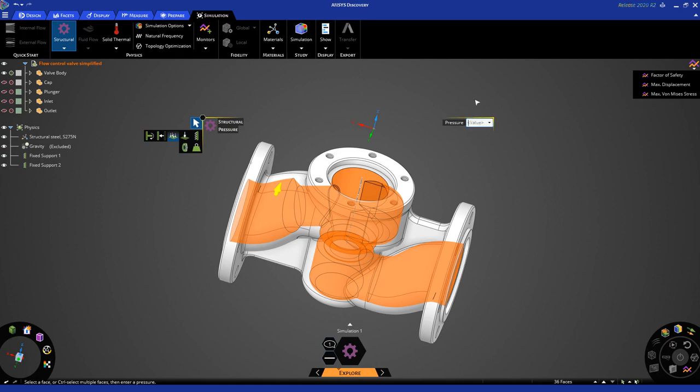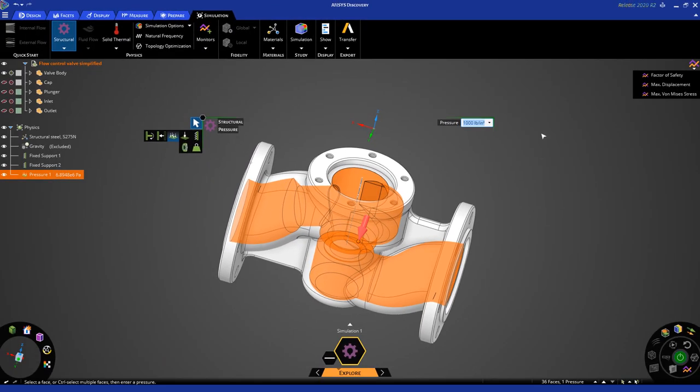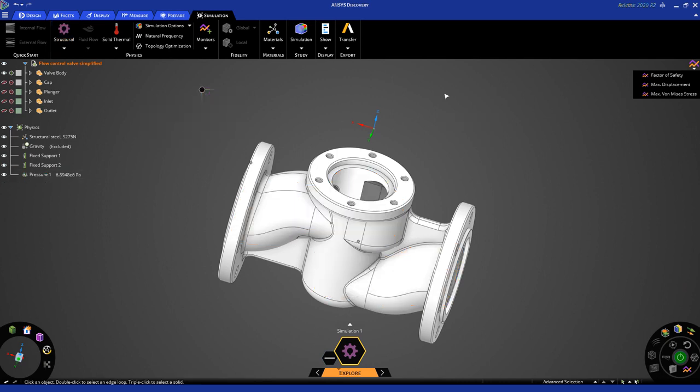Now let's apply a pressure of 1000 psi. So just type in the number 1000. You'll notice that the default units are pascals. You can click here to use a different unit. So let's choose psi. Now I just want you to notice that the heads-up display turns green when you have successfully provided all the inputs you need for that particular tool. So double escape again to exit.